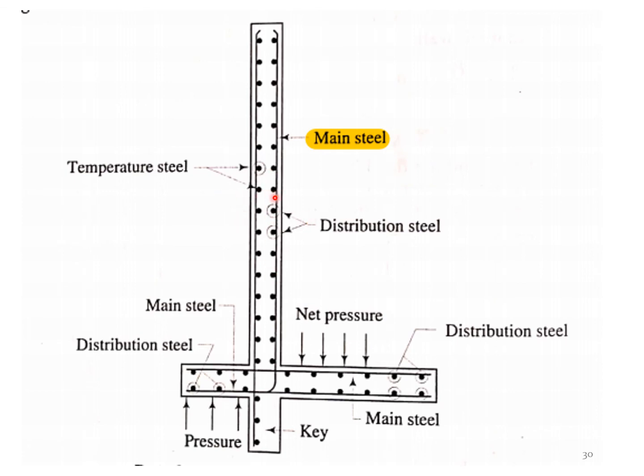If the thickness increases more than 200 mm. If there is a failure against stability or overturning, this kind of shear key can be provided. The cross section of the shear key and the area of steel we provide in the shear key can be made equal to the reinforcement we provide in the stem. And these are the distributed reinforcement bars that are being provided. This is a simple view of the cross section and area of steel that I provide for the retaining wall.